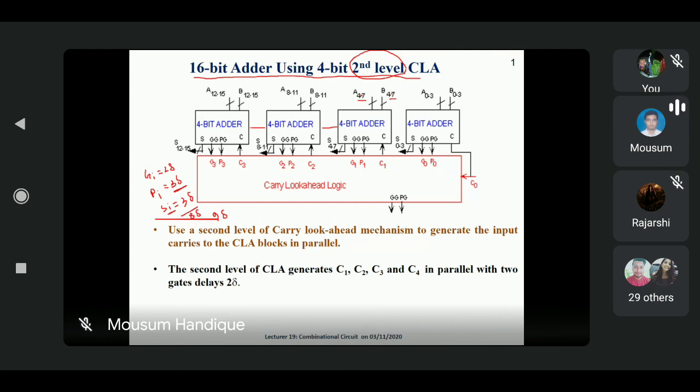When we are talking about the 16-bit adder, what is the connection of this particular 4-bit adder, this particular 4-bit adder, based on the carry? Okay, so if we are designing one level, that time carry is propagated from one adder to the other adder. And when carry is rippling, delay occurs. So again, the time delay is more, though we are using the carry look ahead adder.